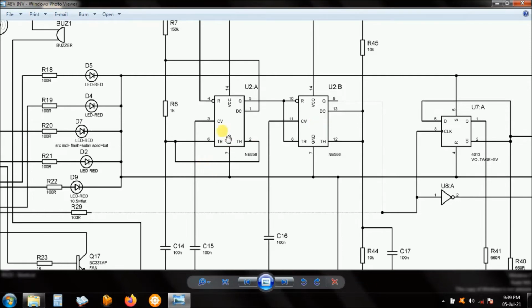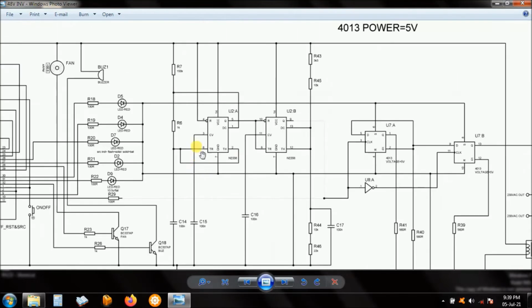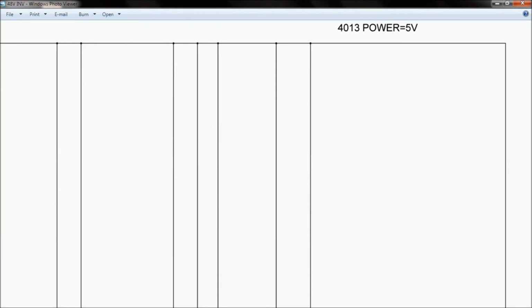This is an astable and this is a monostable, so the frequency is actually set by this resistor and this capacitor. The other components are just for control purposes and maybe just to stabilize it, but otherwise here is the frequency, a 100 Hz output on pin number 5 with low pulses. I think in the previous explanation I actually showed you what I mean by low pulses or high pulses.